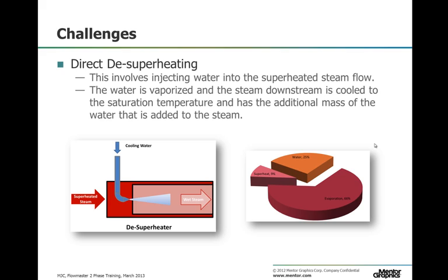These disadvantages mean that superheated steam is generally undesirable for thermal process applications. However, sites exist where superheated steam is raised for power generation, and it makes economic sense to desuperheat some of the steam from some point in the power generation cycle and then use it for process applications. In plants that have superheated steam available for process use, it makes sense to distribute the superheated steam to remote points in the plant, as it will ensure the steam remains dry. This becomes significant if there are long lengths of pipe separating the point of generation and the point of use.